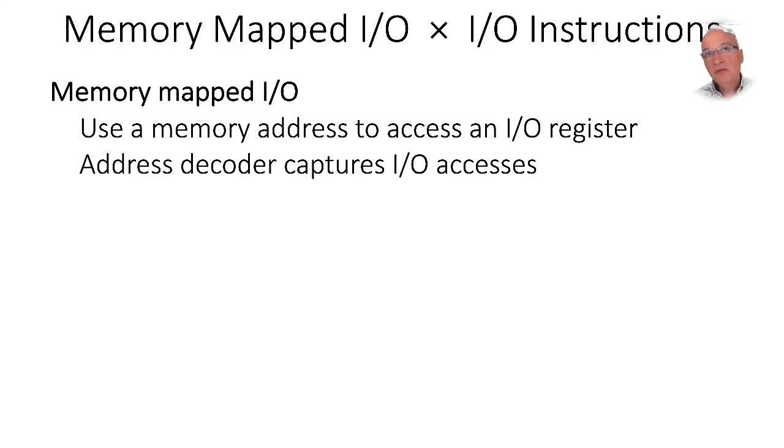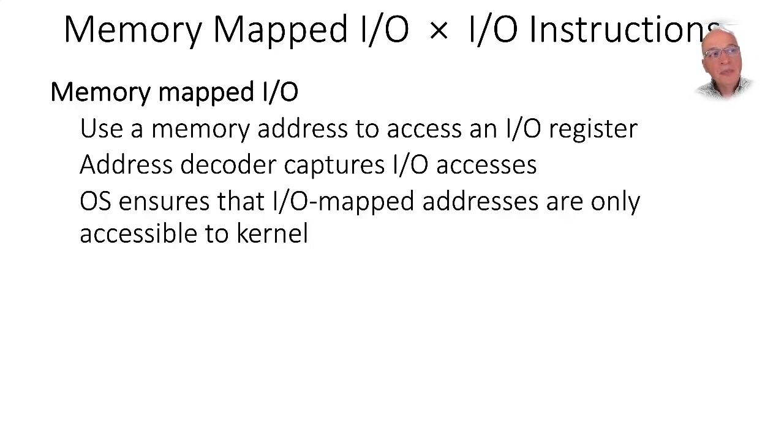Similar to a store, if I want to write into the command register of a device that has been mapped to memory, I'm going to be doing a regular store. In that store, instead of going into the memory, it will go into the I/O device, and taking the operation from going to memory and making it go to the I/O device is done by an address decoder.